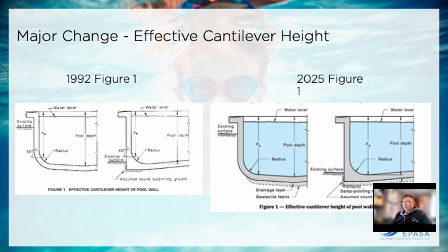to strength. Now, most pools, strength is not always the governing criteria. In fact, it's very rare that it is the governing criteria. But because of this change, strength may well become a governing criteria, and you must take that into consideration. So most pools would have, say, N12s at 300 centres as your standard pool depth. That may no longer be the case. You may find that will reduce down to 250 or even as much as 200. So be aware of that, and please take that into consideration with your costings.